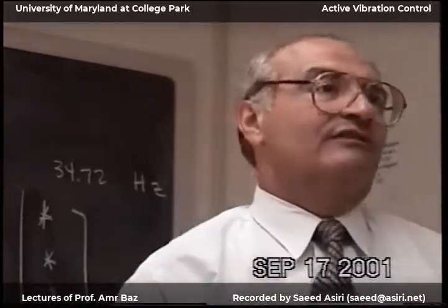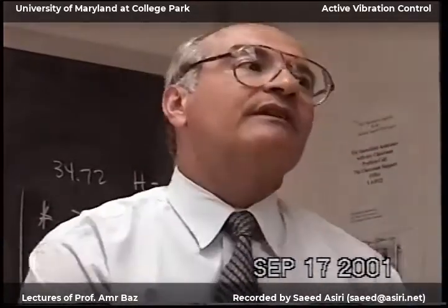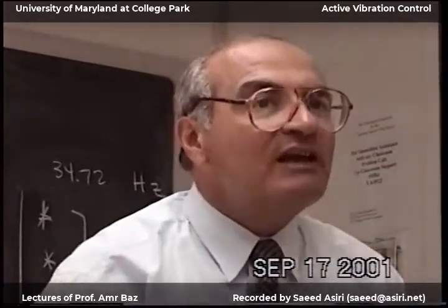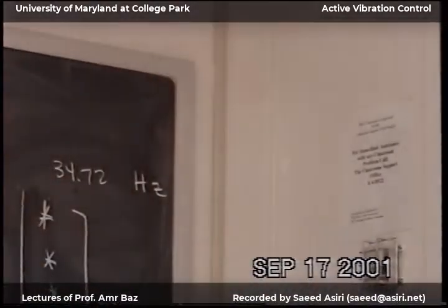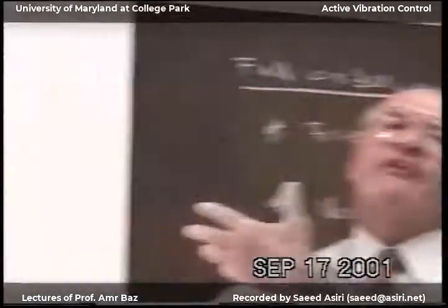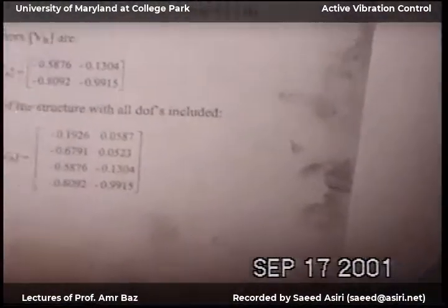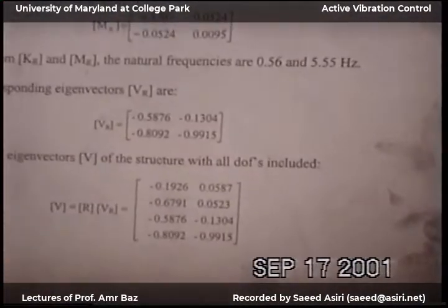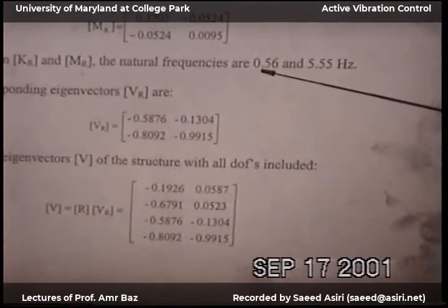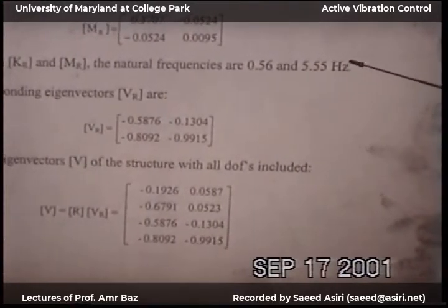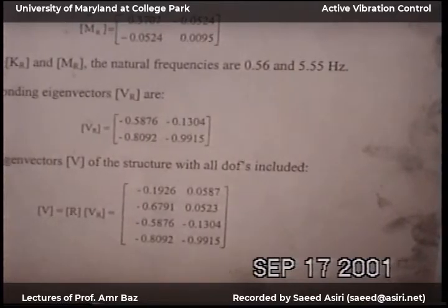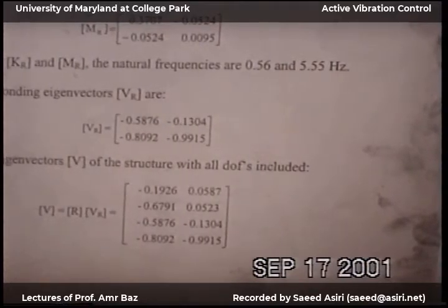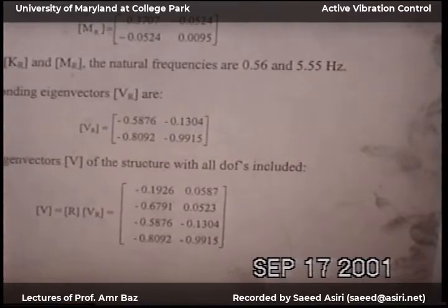So I know that when I sweep the vibration of the engine, I will only excite the frequencies that I have confidence in their values. The other frequencies are meaningless because I'm never going to excite them. The engine will never go to speeds higher than this. So these are mathematical numbers, meaningless. The only thing that I worry about is the frequencies that I'm going to excite. I have to have them correct. I have to have the control on it correct.